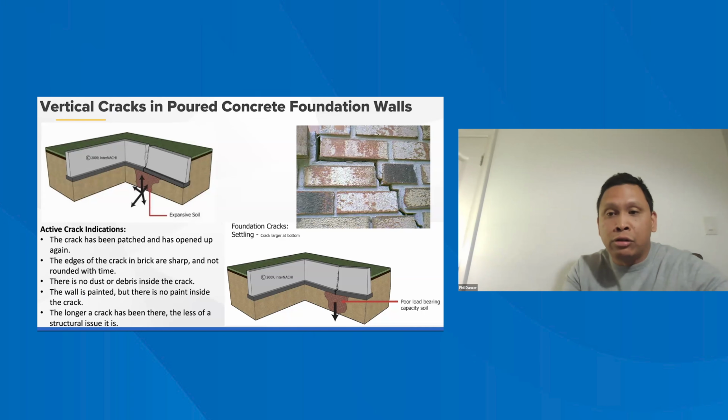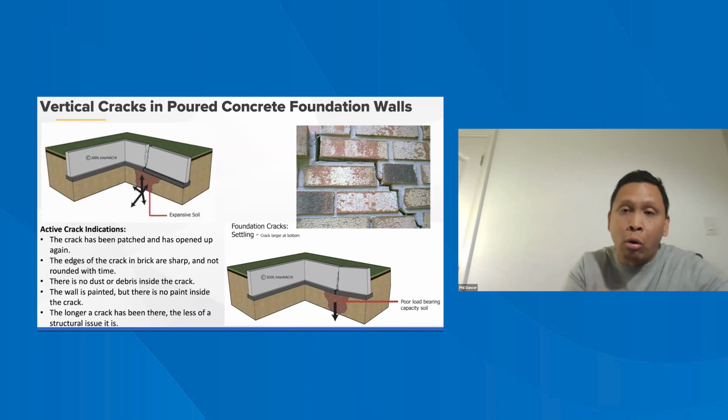If the cause is a shrinkage crack, less of a concern, as opposed to settlement, because as we discussed, concrete cracks. It's just what it does. We just need to be cognizant of how large is the crack, where's that crack centered and located, but then also what are the conditions around the crack that might actually describe why it's there.